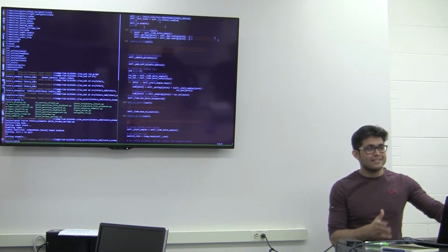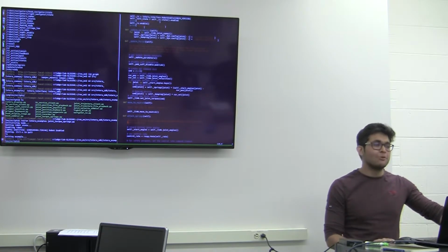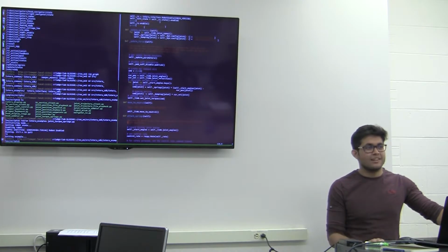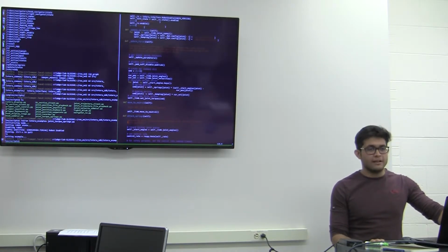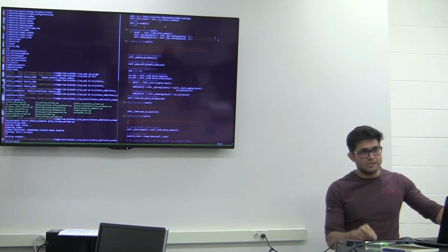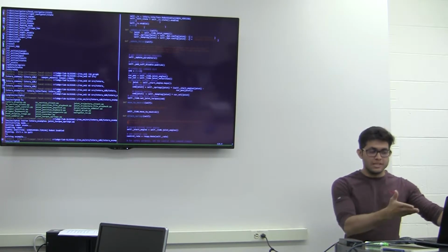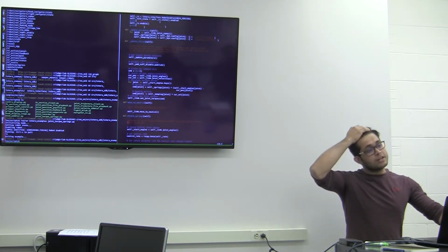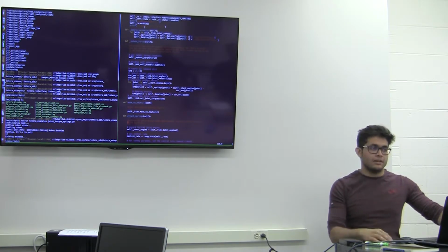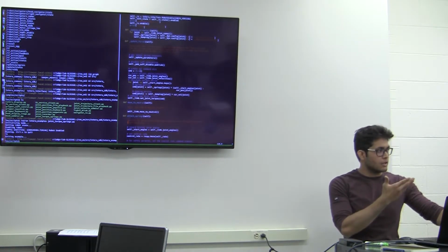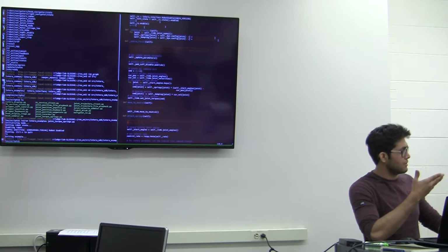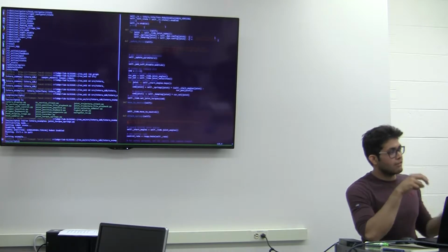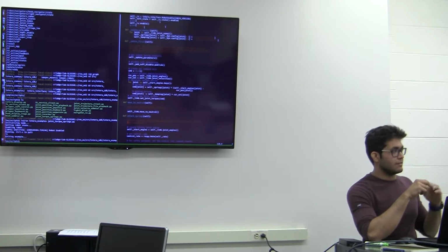If you are in singularity by default, we might be able to get out, but we don't want to keep getting the robot out of singularity for no reason, right? But yes, you can technically go into singularity if you start publishing angles one by one. If you use these commands, you never would. So I would say if you don't need any precise job, just give initial, final, initial, final. I think that's also how you guys did your project. Sorry, it's out of context, but they were working on Baxter and playing tic-tac-toe, right? So you were giving two positions, initial, final, yeah.